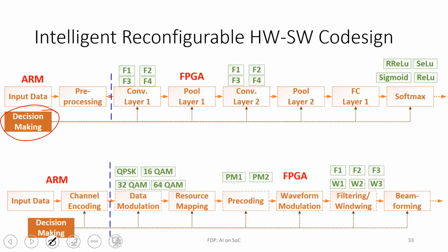So if the customer wants that, okay, this is the product I want to use it with, I don't want future upgradability, okay, this is the one. But here the customer wants a future one, then this will be the case. For example, the service operator, the cellular one, they are now going from complete hardware of 100% ASIC to at least 50% FPGA and 50% ASIC. So it is all the application one, but anyone who learns to develop the algorithms for the FPGA will be able to do it for the ASIC as well, because till the RTL part, it remains the same.